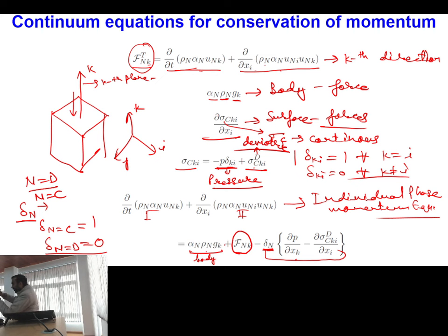Because of that velocity, there will be interfacial shear with the continuous phase. Second, say dispersed phase is stationary, but your continuous phase is moving. Then also it will apply certain amount of force, and more important, we will always experience some sort of relative velocity between the continuous and the dispersed phase, and that relative velocity will apply certain amount of forces on the body.